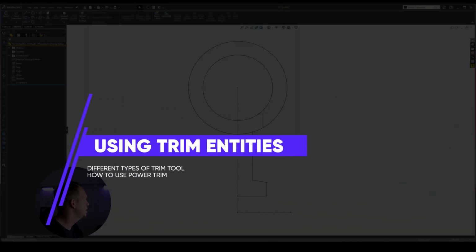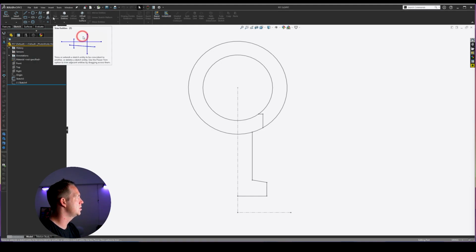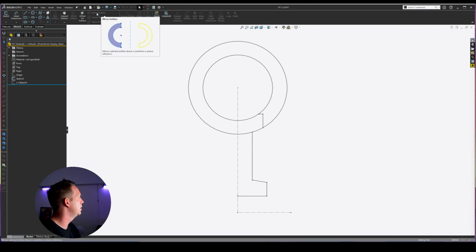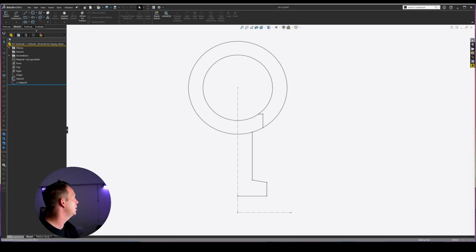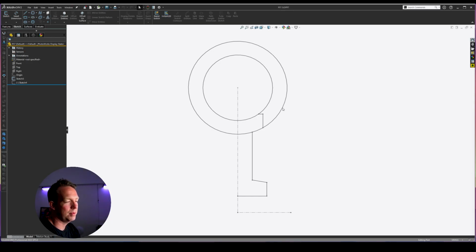Okay, hey guys, in this lecture, we are looking at refinement tools for sketches. What that relates to is, on the sketch toolbar, not creating the geometry with the lines and rectangles and circles, but actually manipulating that geometry using other tools such as trim, convert, offset, and I'll also look at mirror. For the CSWA, the only tools it lists are offset, convert, and trim. So no mirror is listed, but we'll show that one anyway because it's a fundamental tool to simplifying your workflow. So we're back to our part.